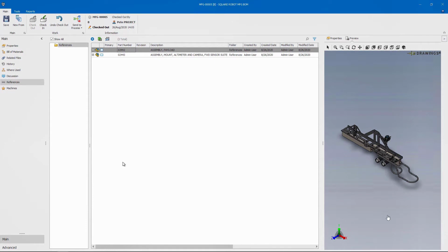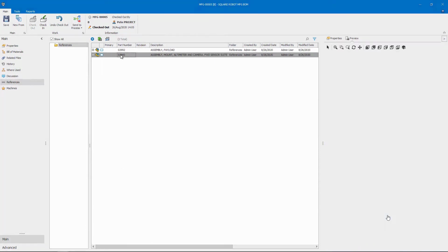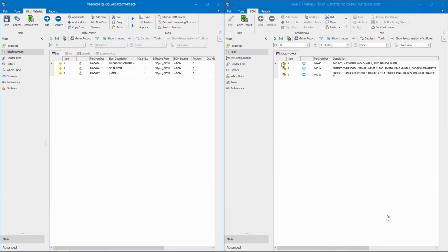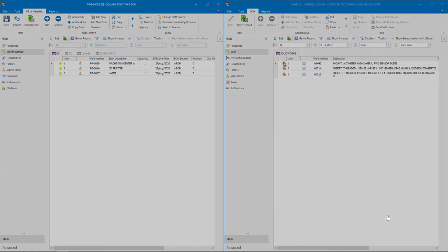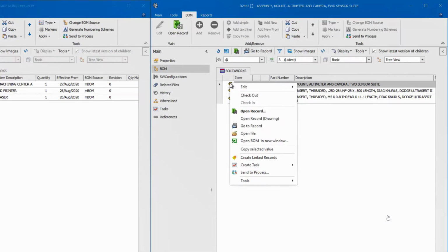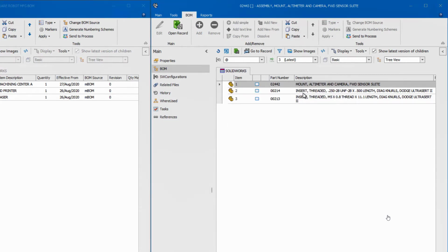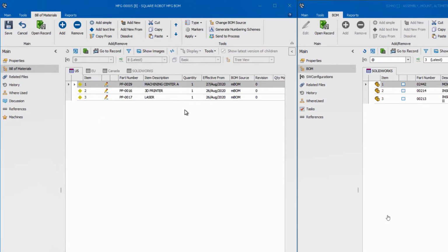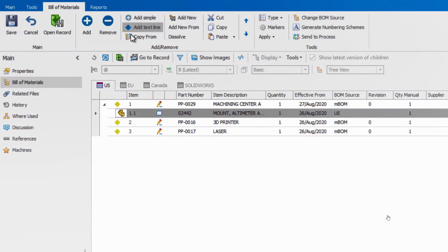Items are a way to correlate design data in Manage. If we look at this item record here, it's looking at a number of assemblies that need to be consolidated into a manufacturing bill of material. Now in Manage 2021, we have these windows that are modeless, so I can easily copy data from one window to another without having to switch from one to another full screen.